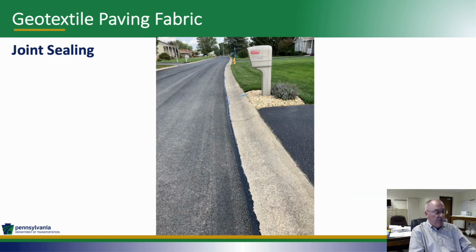The last part of the project involves the contractor, where he's required to seal all finished joints with rubberized joint sealing material upon completion of the paving. Not only does he seal along the curb, but he'd also seal the center longitudinal joint down the road.